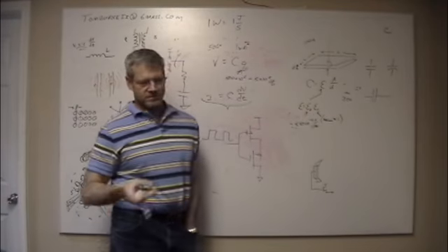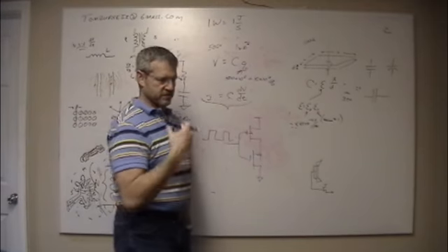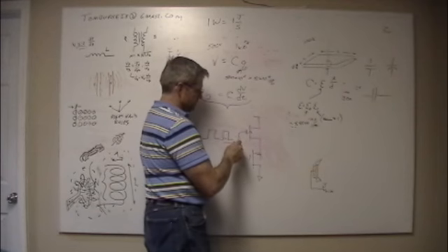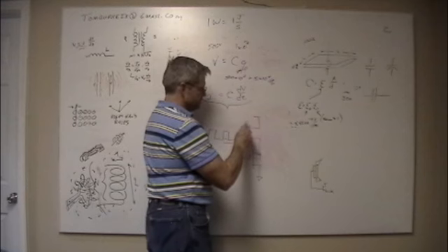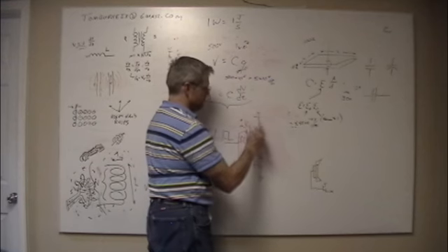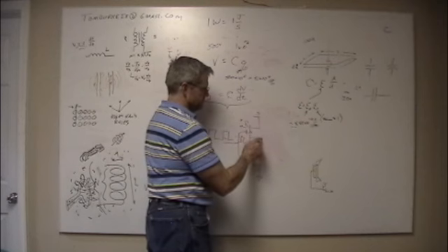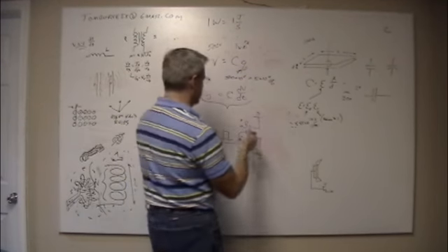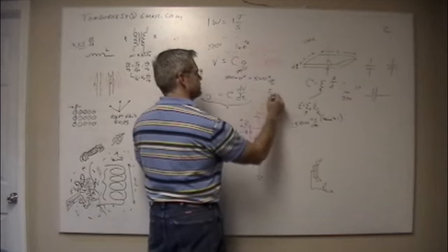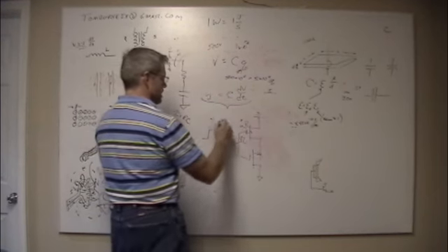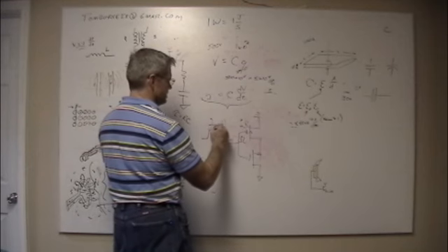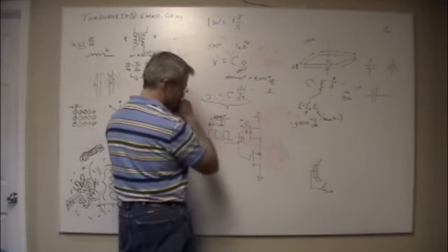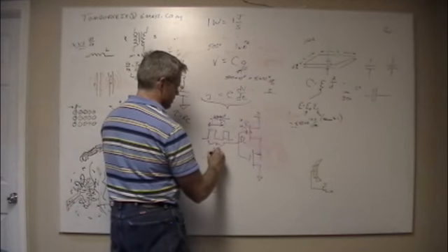And bigger capacitance and lower capacitance, whatever, builds sort of its own time constant because of the internal resistance. So as this, let's call it 5 volts logic, goes through, I get 5 volts here, and I get a 5 volt spike here, which is 0 to 5 volts. Just a minute ago, this was probably at 0 volts here. Now I say C is, these are nanofarads and picofarads, so dV is 5 volts. If I'm running at 1 megahertz, that means from here to here is 1 times 10 to the 6th per second, which means this is 1 microsecond.